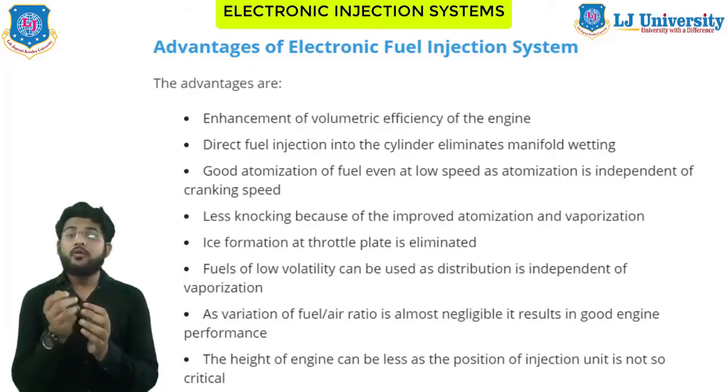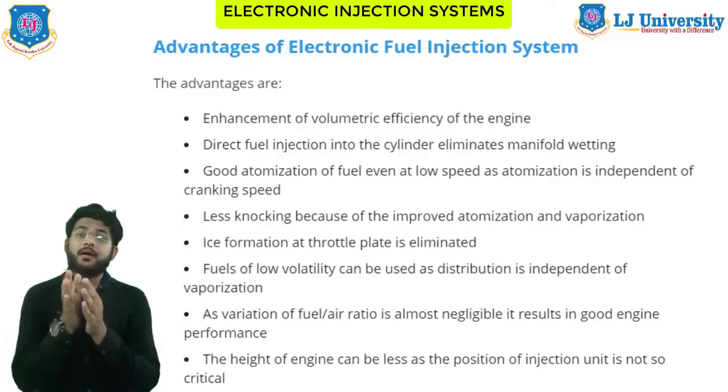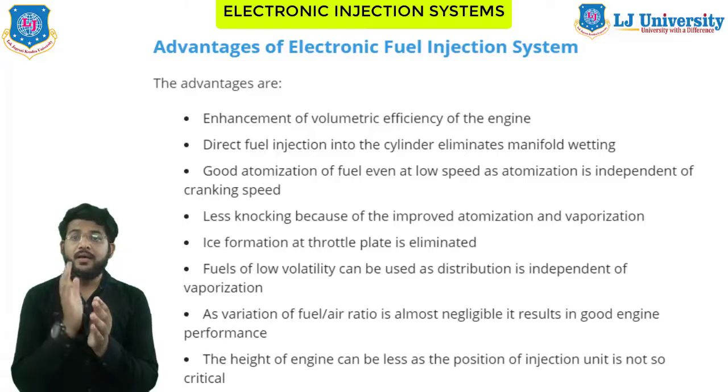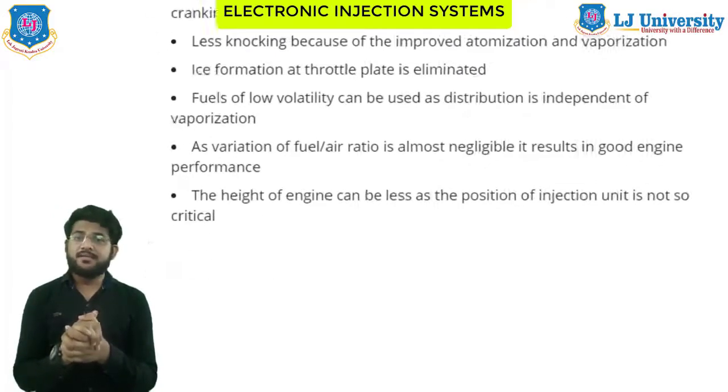Thereafter, fuel of low volatility can also be used as the distribution is independent of vaporization. Okay, so you can use any of the fuels. Thereafter, as the variation of the fuel air ratio is almost negligible, it results in good engine performance. Fine. Thereafter, the height of the engine can be less as the position of the injector units is not that critical. So this was all about the advantages of the EFI system.